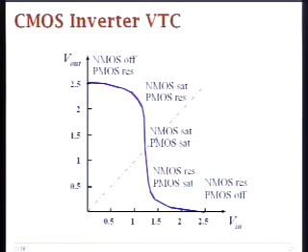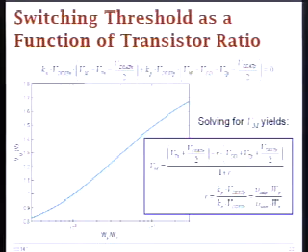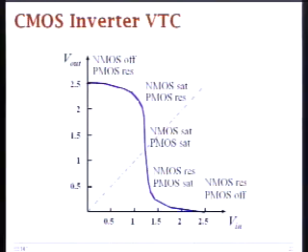And when you plot this VTC, you have to equate currents, and you need to make sure that you verify the mode of operation for both of your devices. Make an assumption, carry the derivation through, and do it again. So now, a very important parameter for this voltage transfer characteristic is exactly this switching threshold. And it is very important to be able to analyze this curve and calculate this intersection point. So what are the important assumptions that we need to make in order to calculate the switching threshold?